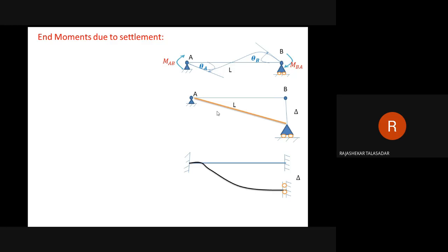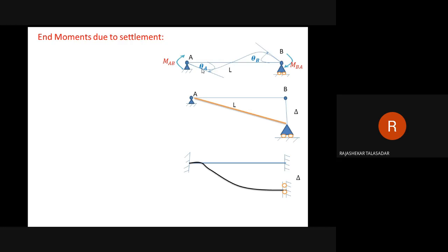Now, this is when both ends are pinned. Now, if you look at this figure, right? What is this? This is a beam having a fixed end at both. Now, you know that fixed end means the slope will be 0. So therefore, this elastic curve or deflection curve initially comes in line with the axis, then it deviates and comes like this. Here, if you see, initially this line comes in line with that, whereas at pinned, it suddenly starts deviating like this. Okay, that is the difference between the elastic curve at pinned support as well as fixed support.